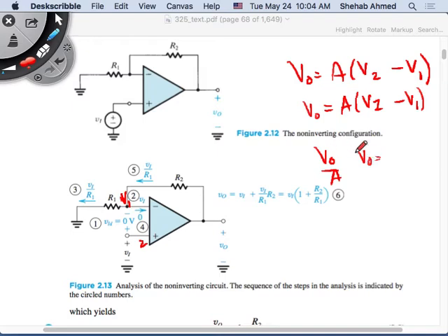One second. It will be driven to 0 if I assume that this is infinite gain. Remember the calculation, the circuit that we did before? Having the feedback will drive it to 0, or to something depending on the gain and the value of the DC source. Remember we had two sources? A resistor here and a source, and a resistor here with another source. So I can drive this voltage to 0 if I make these two resistors equal and I make these two sources equal, for example.